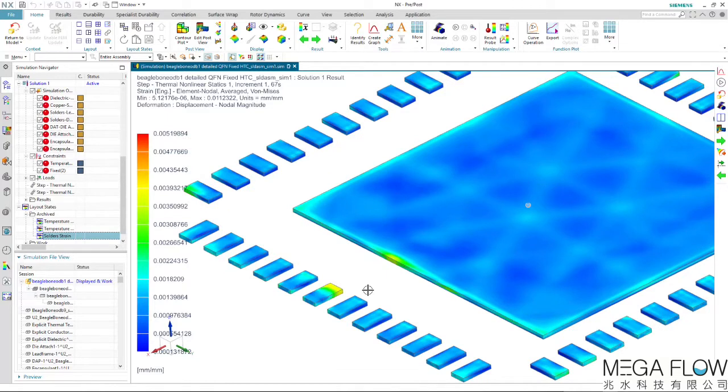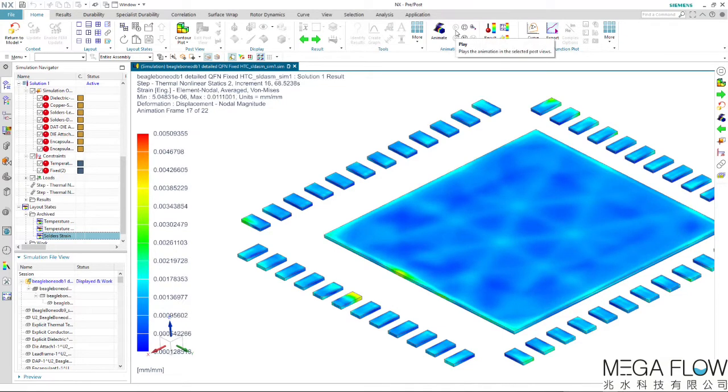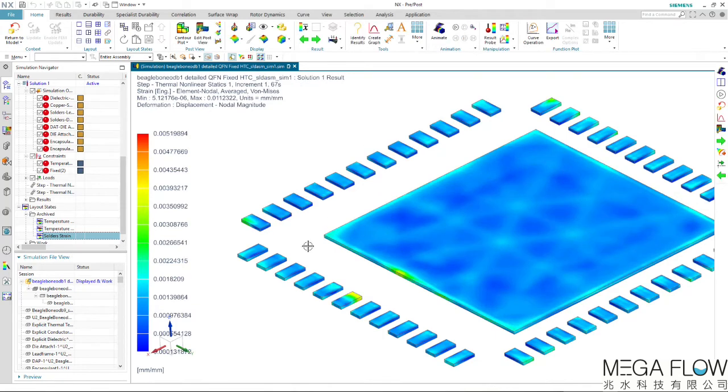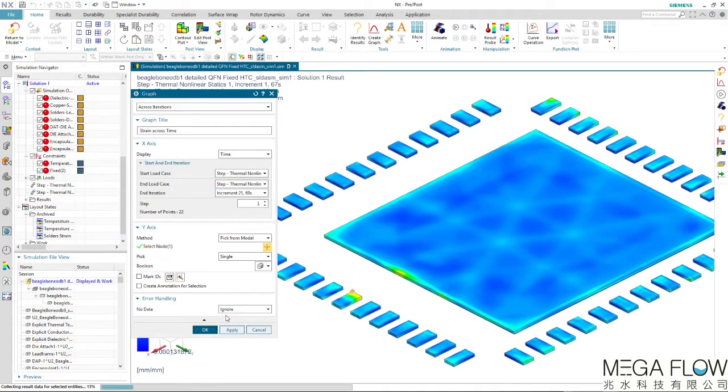After the solve, we can directly open the results on the same user interface and define post-processing activities. At this stage, we were able to perform a thermo-mechanical analysis of a solder joint, where we can deduce the temperature, the stress, and the strain between the solder and the leads. The transient variation of the strain at the selected point of the largest strain is plotted throughout the cycle.